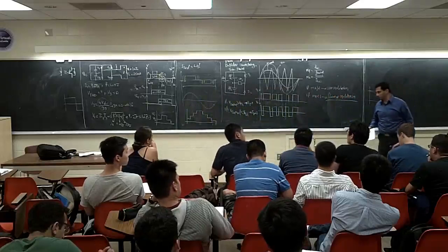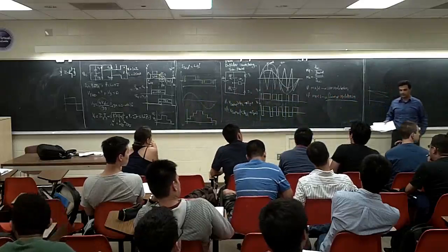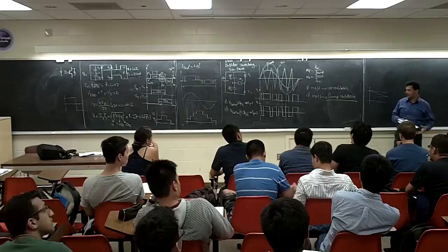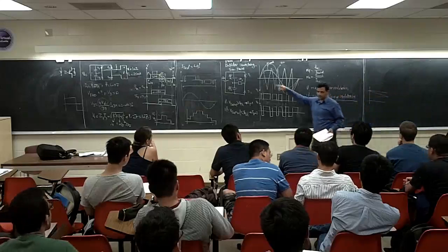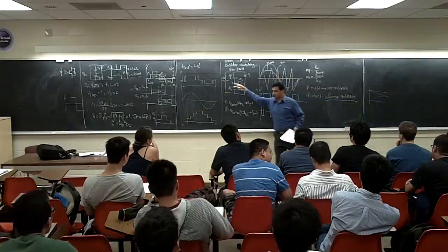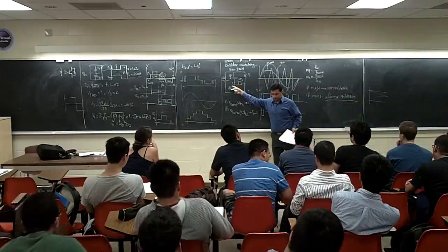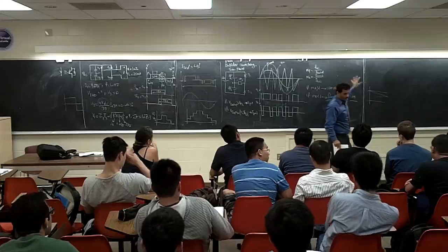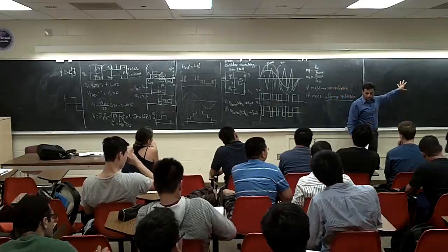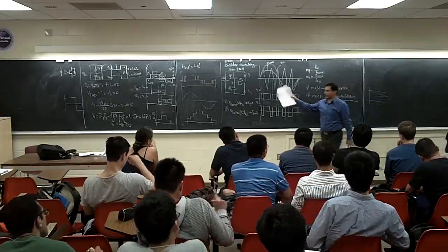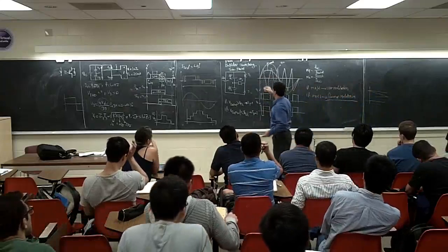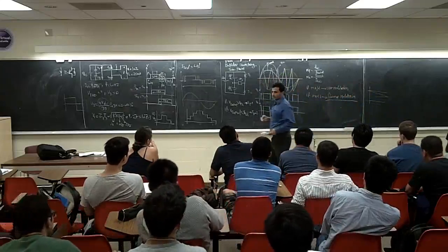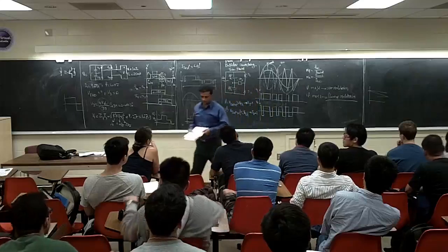We're over the time. I don't want to go down this path, because it's going to take time, and there's a little bit of math involved. But keep this one in mind. This one was a sine PWM for the half bridge. Next class, I'm going to continue with the same thing, MA, MF, modulation, and go to the full bridge with bipolar. I didn't talk about the bipolar. Bipolar basically has another waveform here, like this. We'll talk about that in the next class.